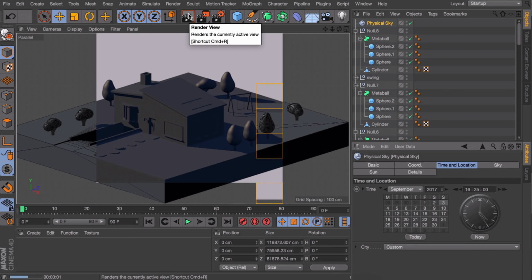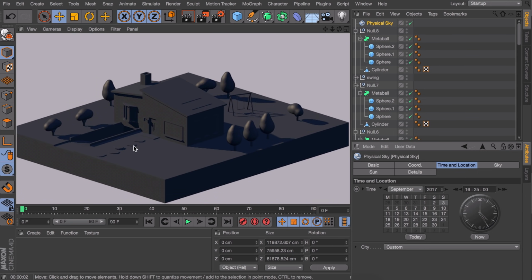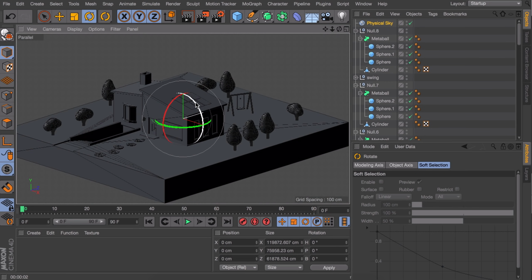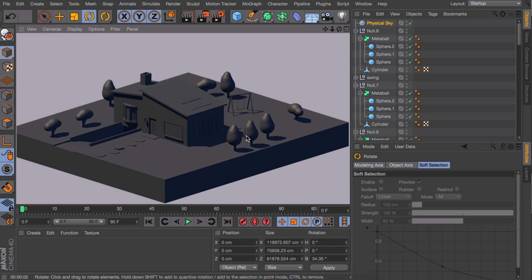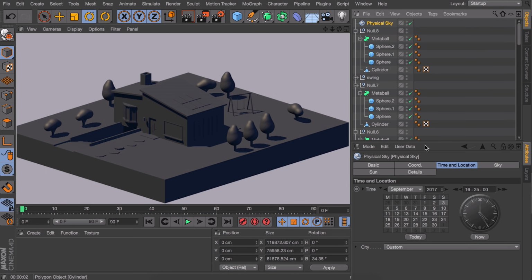These are giving me some nice angled shadows, but I find them to be a little too long. So a trick I use for this is just rotating the sky a little so it hits the scene more from above instead of from the side. Right now you can also notice how dark these shadows are. The windows are even barely visible at the side.